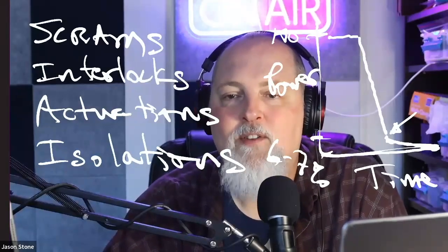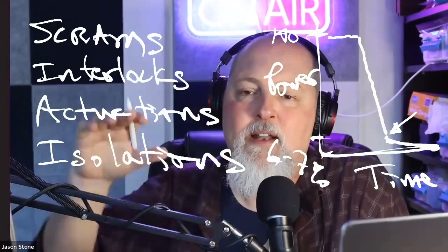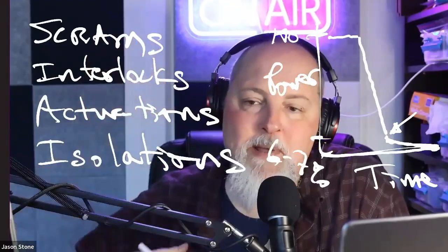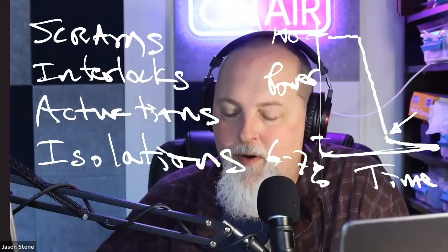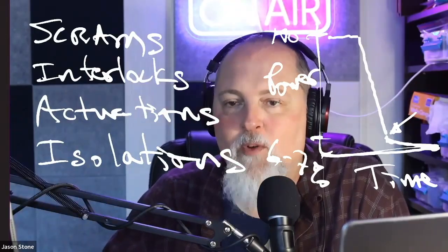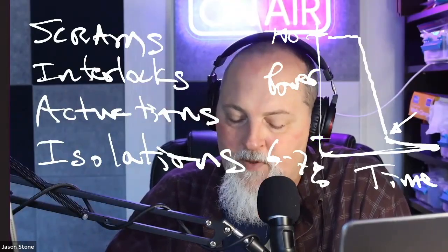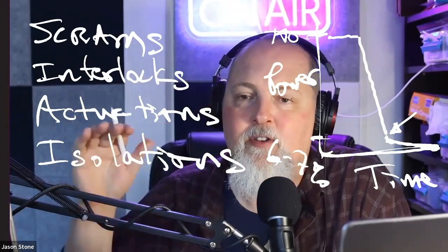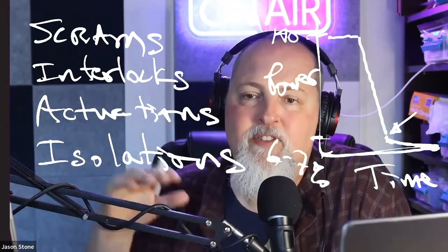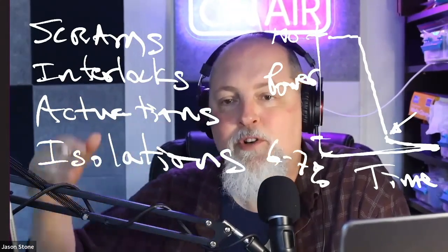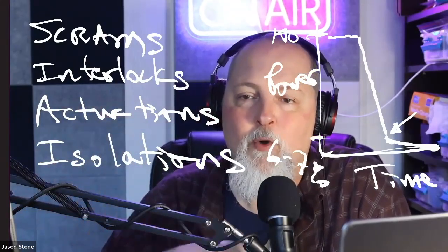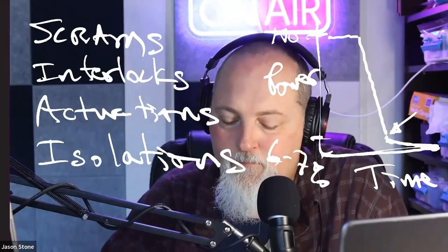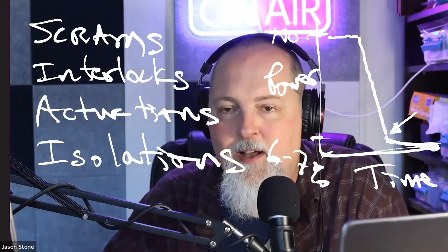We put the control rods in, and that immediate heat from the fission stops. But we still have some fissions going on, and that's our decay heat once all the control rods are in. This decay heat starts to slow down. It's subcritical, so there's no more chain reaction, and the number of fissions is getting fewer and fewer. But this can be a long time.